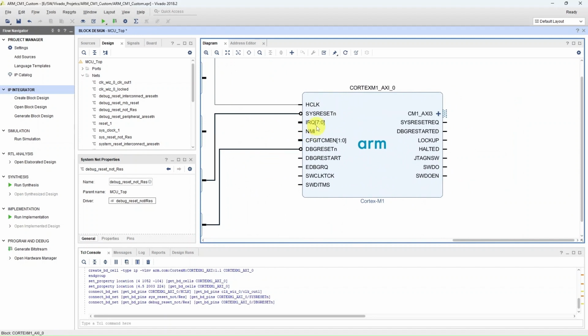So at this point we have few other signals such as the interrupt signals, the non-maskable interrupt NMI, and then this is for configuring the ITCM, that is the instruction tightly coupled memory enable. So these bits will indicate the upper alias or the lower alias to use from the ITCM memory region.